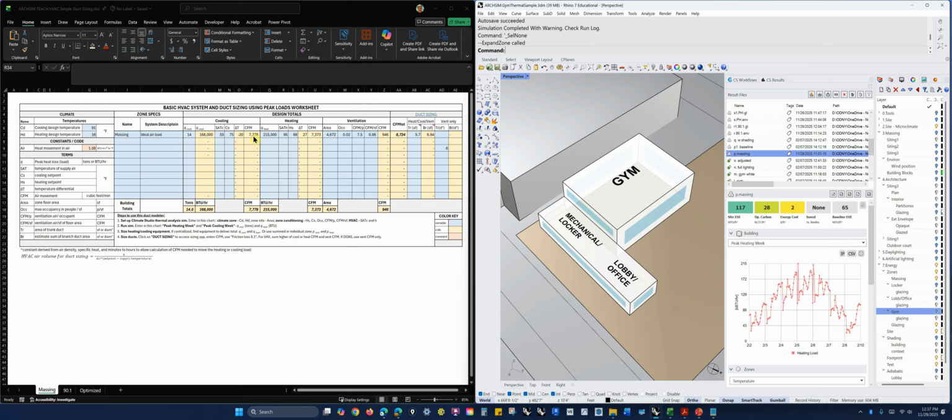Well, basically, it's just a function of the set point for the zone. So in this case, I'm going to set my cooling set point at 75 degrees. I think that's a fairly common cooling set point, especially in commercial buildings. Then I need to know what my supply air temperature is, and so I've got these terms clearly identified over here.